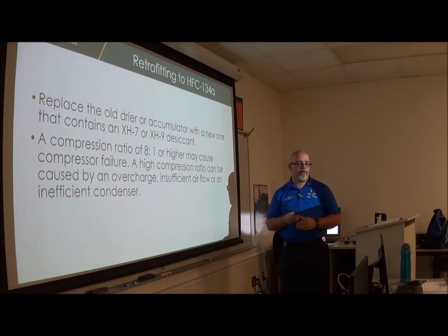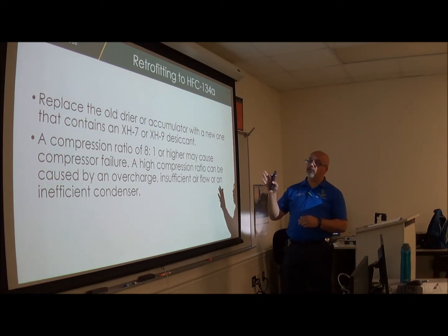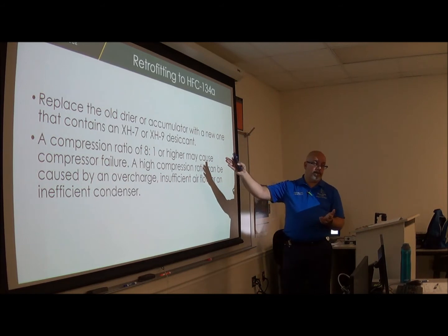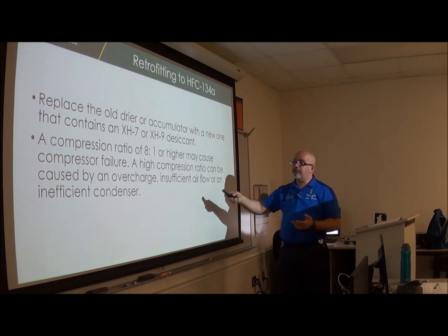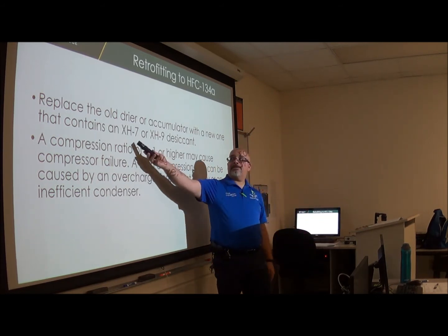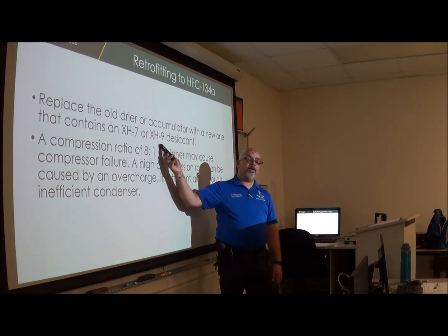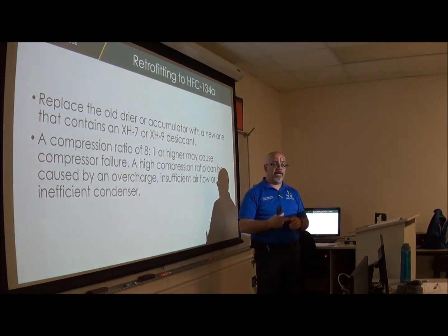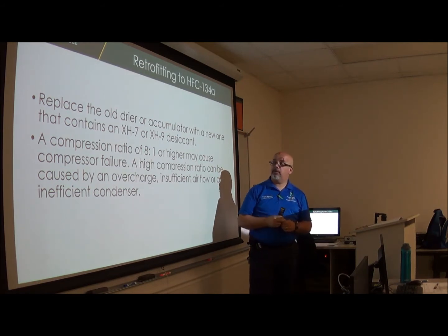So you said you have to replace the dryer and the compressor? No, we need to replace the dryer or accumulator, which is the other name. We would have to change it from the XH7 to the XH9. Okay, and then we would also replace the O-rings, from the black ones to the green ones.